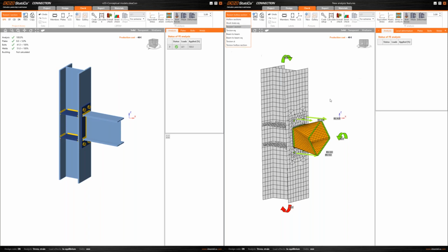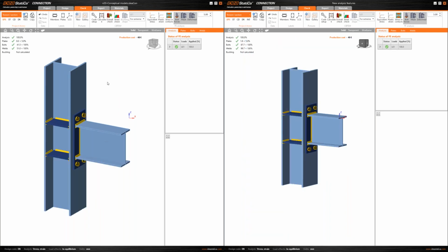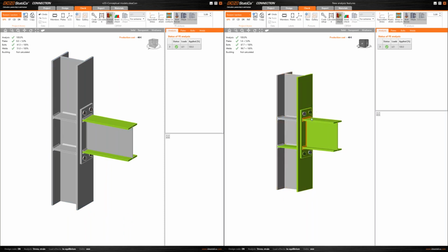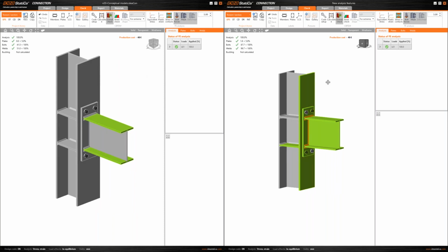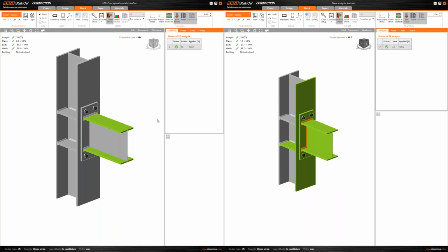Here, results are very different. We can already see this from the overall check, where now we have some parts of this model that are in the green area, while in the previous model they were in the gray area, meaning that they were not even plastified at all. Again, this is an idealized model to enhance the differences between the two versions, because we have an open section that is under torsional load. Usually we have open sections under both bending and torsional loads.